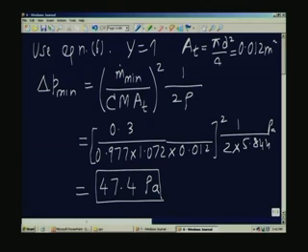This is the formula, obtained from the characteristic of the Venturi. C and m are already determined. All I have to do is plug in all those values. So m dot is 0.3, C is 0.977, m is 1.072, and AT is 0.012. That is what is calculated here.